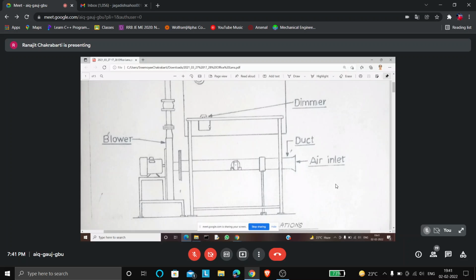The secondary winding has a large number of turns, which can be changed by rotating this disk. So if you rotate the disk, you change the number of turns of the secondary winding, and the potential difference across the secondary winding can be changed. Now, the heater here cannot withstand a voltage as high as the AC supply voltage.